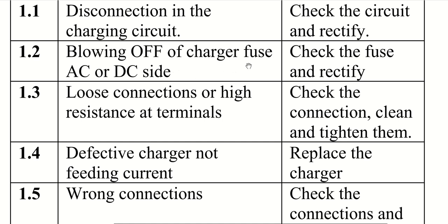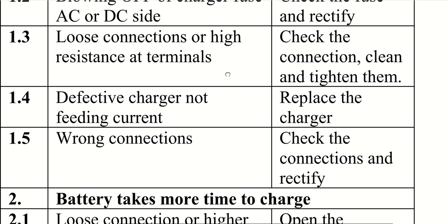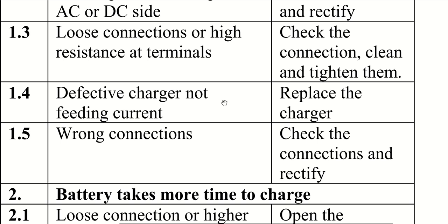As the rectifier has got an AC side and a DC side, you should check the fuse on both sides, and if there is a problem, you can check it with the multimeter, of course. Needless to tell this, but okay. So check the fuse and rectify the problem if any problem is there related to the fuse.